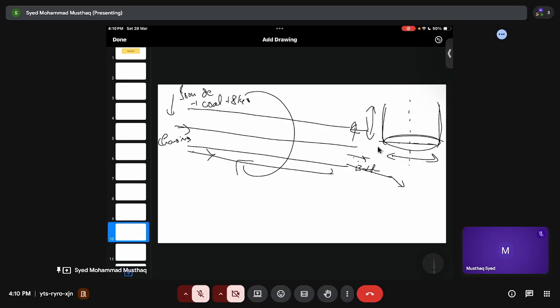You have your coal gasification, you have your coal, you purge oxygen, then you do the cleaning, because whenever you burn coal, as we have discussed before, coal contains moisture, sulfur, and different things. The silica will not get oxidized or evaporated. So that's why you need to do the gas cleaning,